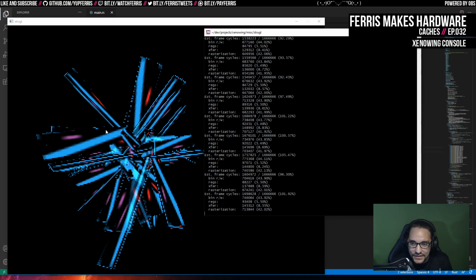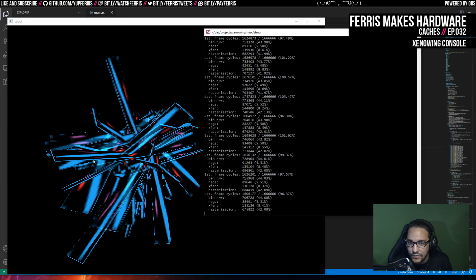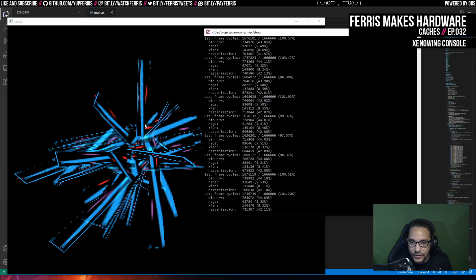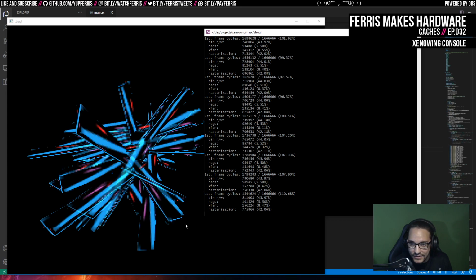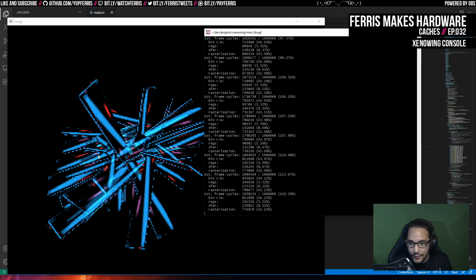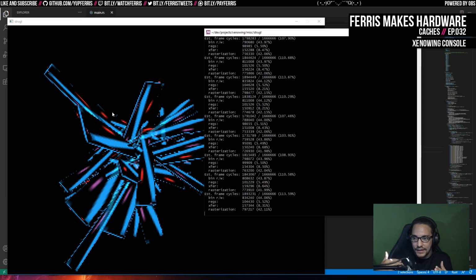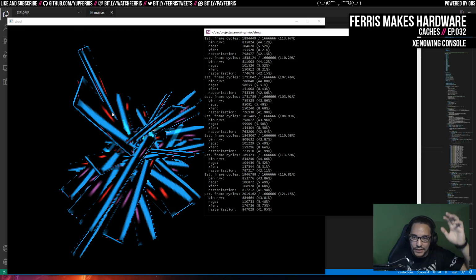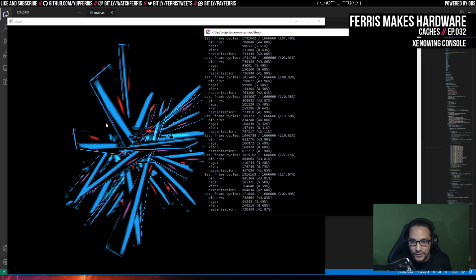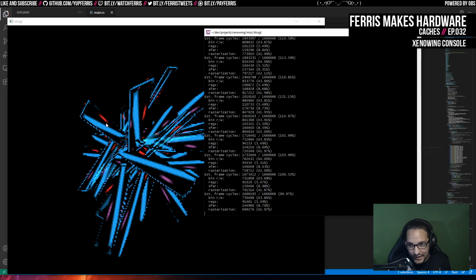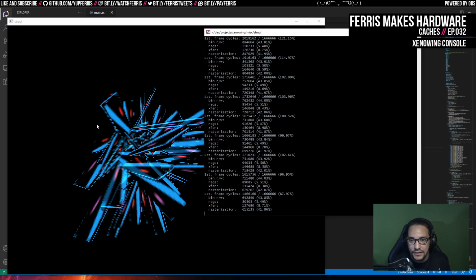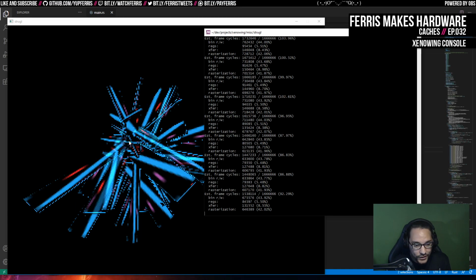But yeah, I don't know if I mentioned this, but right now the architecture, for every draw call, creates a new list of bins and pulls all the data in and out of memory for every draw call. And I actually want to overlap draw calls, so that each tile bin contains triangles from multiple draw calls put together. That's kind of the ideal case, because then you only ship color memory in and out of the tile once per frame.